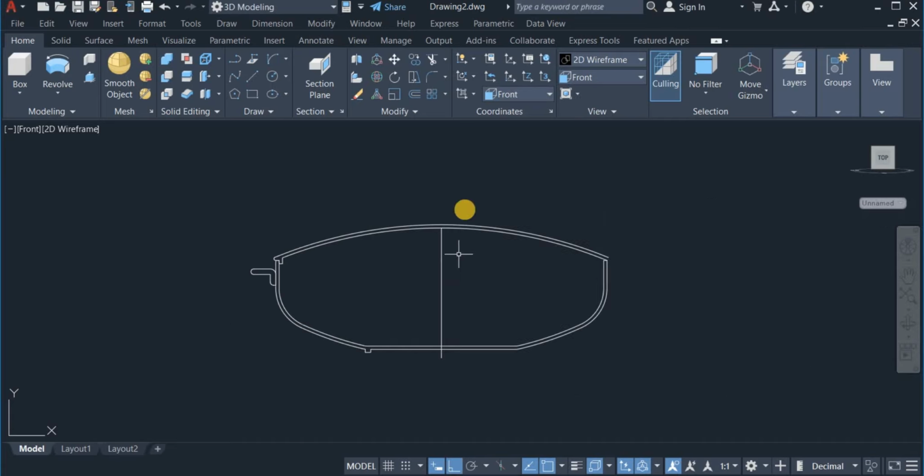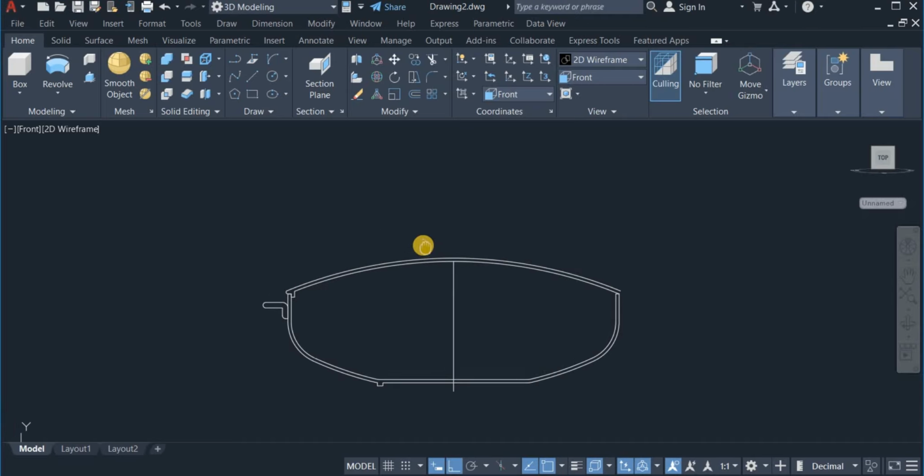Okay. Also again, I'm going to create the top handle. That's the handle for the dish cover. So I'm going to use the polyline as well to do that. So come over to the draw panel and click on polyline. Now first draw a line horizontally of 25.